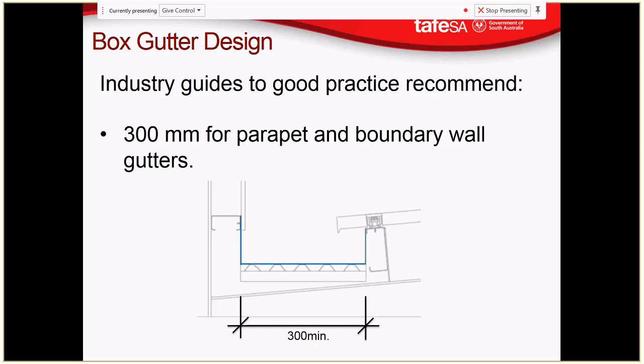And yeah, so I mentioned I'm just pulling figures out of the air. I haven't calculated it on my phone or so. But let's say that a 1 in 200 slope over 50 metres is actually 100 millimetres. When you've got details like this, the draftsperson can draw that up and go, oh yeah, look, our purlins are 250 high. We've got it on a cleat, picking it up 50 millimetres above that.